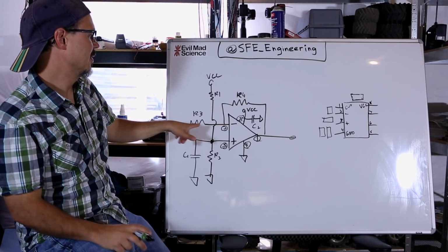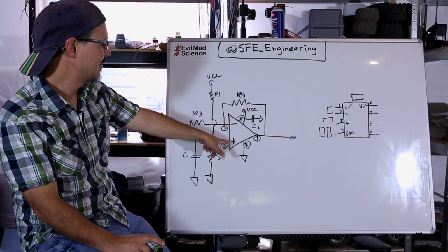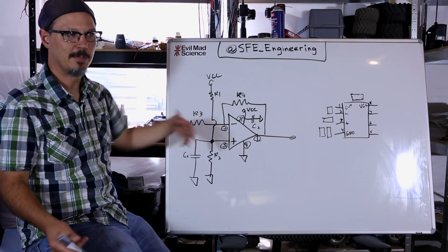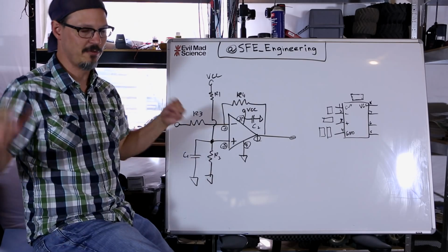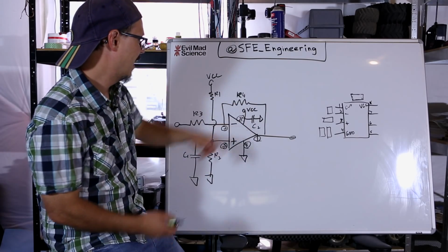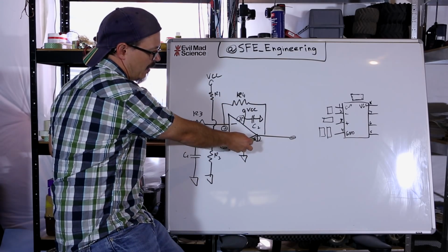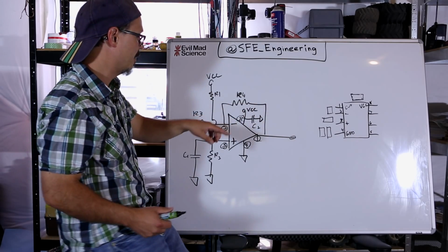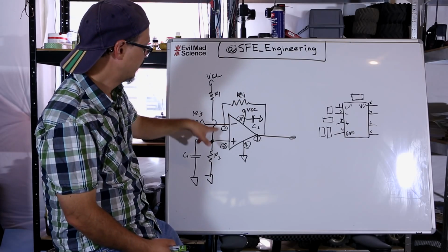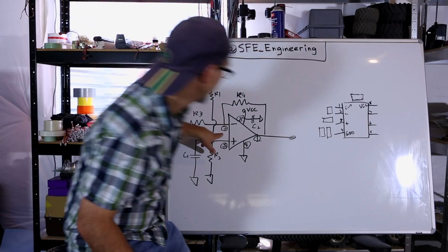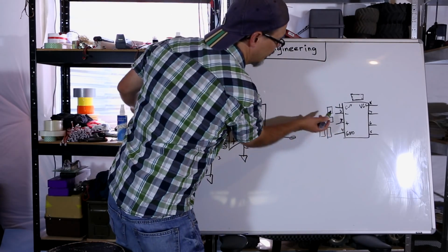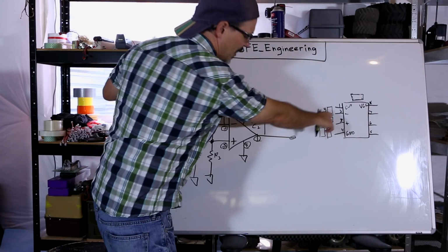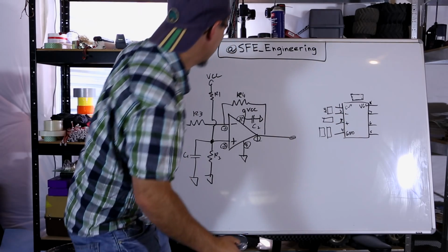I'll start with the critical ones. Anything that attaches to one of the high impedance lines here. Those paths have to be pretty tight. You try for tightness. You try to keep them very close, right? Start with my feedback, right? Pin 1 is the output for one of the 2 op-amps on that chip. And I've got R4 that goes straight over to R2. So what I've done over here is I've placed this guy, and this represents R4. So I would put this guy right on those 2 pins.